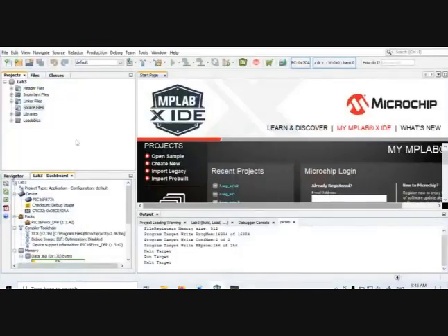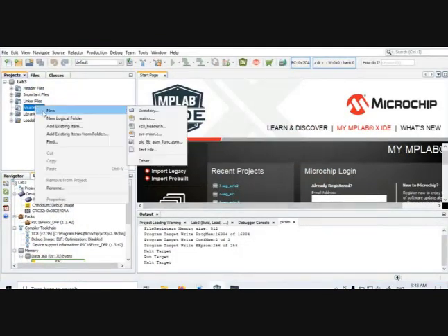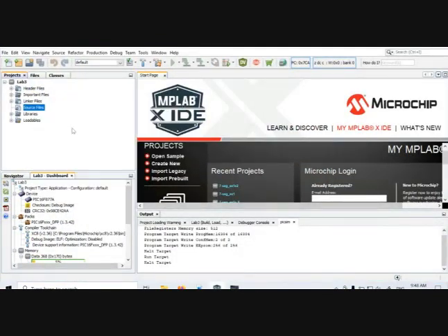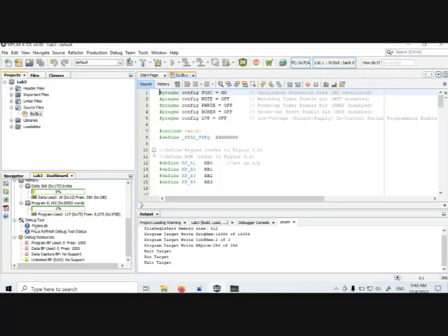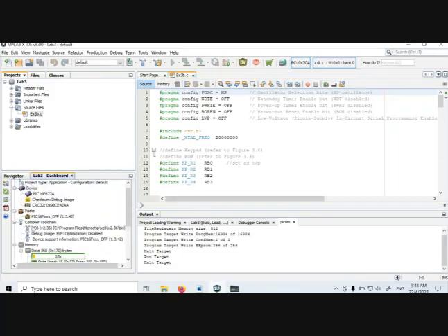And then go to the program side. Create a program. This one is already included. Before you do anything, make sure you pick the same lab, XC8, and then this one. The microcontroller of choice, PIC 16F877A. The clock frequency is at 20 MHz.